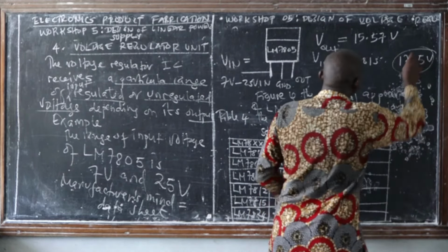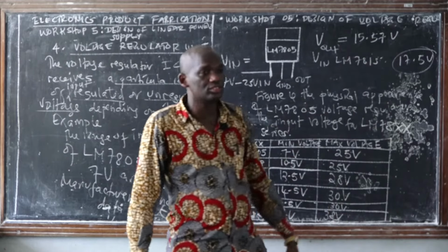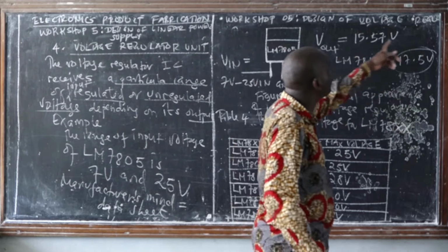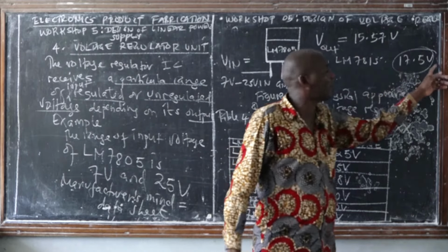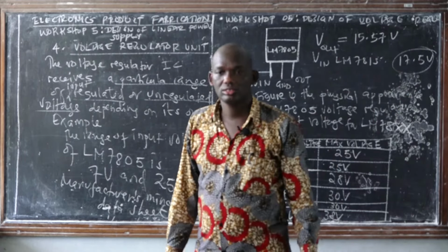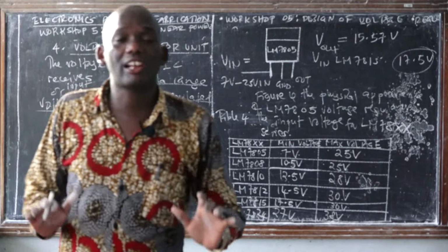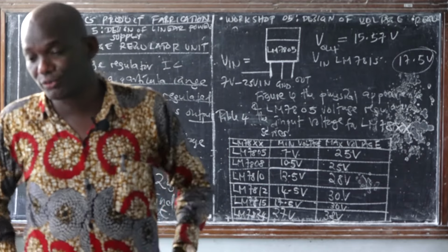But your input voltage is 15.57 volt. Is 15.57 volt greater than 17.25 volt or not? It is less. So from there, don't expect that voltage regulator to regulate and give you 15 volt.